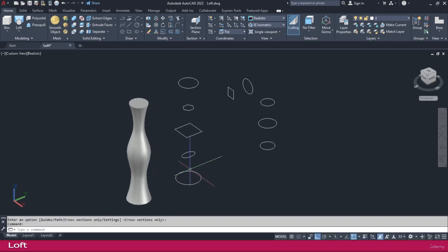You can use any sketches. Before, I made all circles only, but here I used first one circle, then this ellipse, here a rectangle, a polygon, and again a circle. This also we can convert to loft. Go to the loft and select the first one and the next one and the next one and the next one and the next one and enter. Double enter, it is ready.